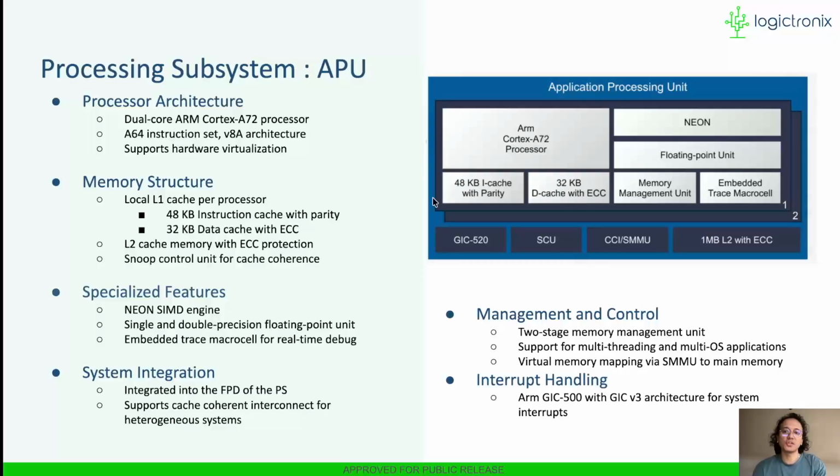It also has a Neon SIMD engine and single and double precision floating point units. For management and control, it has a 2-stage memory management unit, and it supports multi-threading, multi-OS applications along with Versal memory mapping. The interrupt handling in APU is ARM GIC 500.